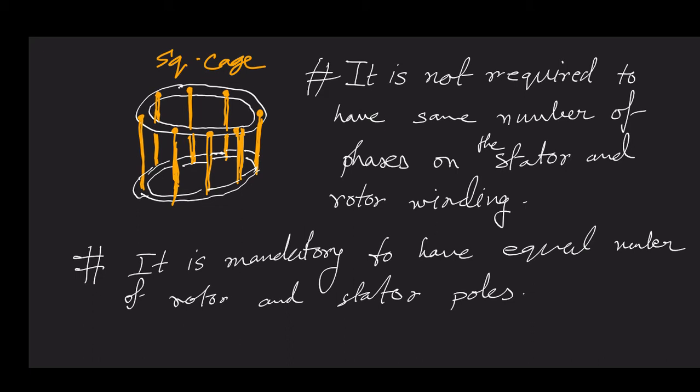But you are giving current to both rotor and stator, and there is some magnetic interaction between the rotor current and stator flux, and that causes either magnetic interlocking or a kind of repulsion that produces the torque. In case of synchronous machine, it is the magnetic interlocking that makes your rotor rotate.